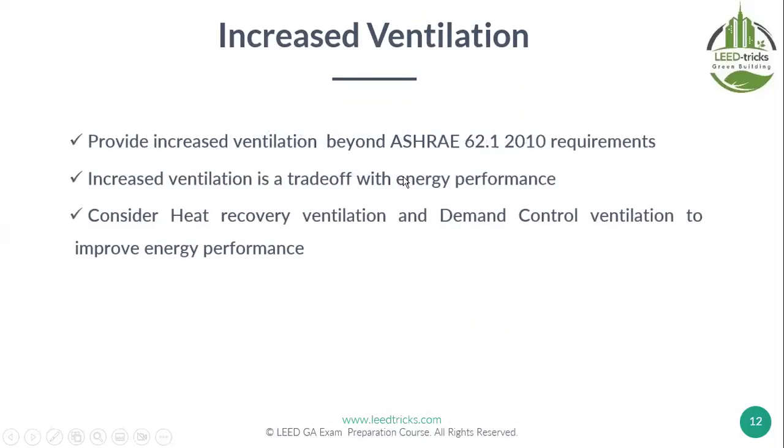Increase ventilation. So if I want to improve the air quality, you need to increase the ventilation. And this makes sense, because without increasing the ventilation, how can you increase or improve the air quality? You need new air, fresh air from outdoors. The more outdoor air you bring inside the space, the cleaner the air is, of course, and this air can be better than the indoor air that is 5 times more polluted than the outdoor. But the issue is that this air is hot.